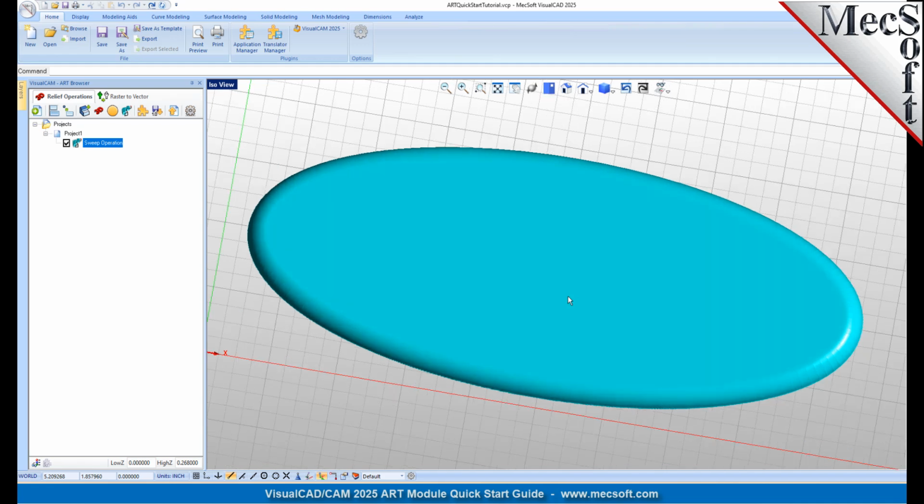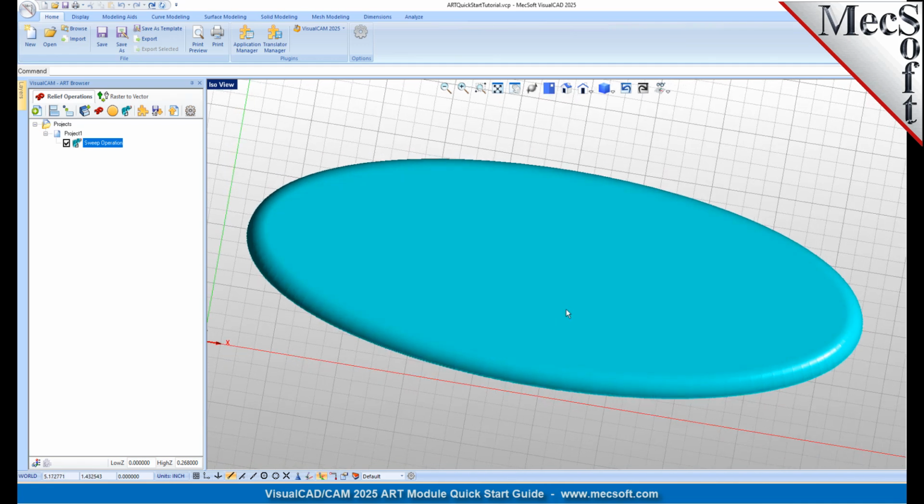Our next operation will be to create a puff volume. The Create Puff operation allows you to select one or more border curves and puff up the insides using a shape function that can be selected from a predefined list. The shape of the puff can be further affected by selecting detail curves inside the border curves. Let's have a look.